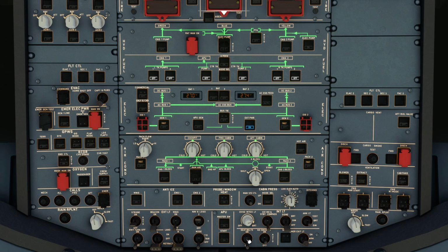No smoking auto. Seatbelt signs can go on. You'd set the seatbelt signs to the on position after you are done with the refueling. Okay, cabin pressure, landing elevation set to auto. Here you can adjust the cockpit and the forward and aft cabin temperatures. Alright, on the hydraulic panel there's nothing to set up. We can turn on all the fuel pumps by extinguishing all the white lights.